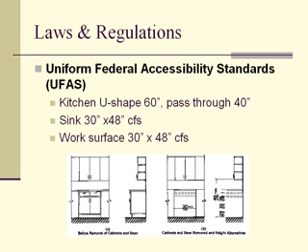The idea also is to provide the 30-inch clear floor space that we have spoken about at each of the appliances: the washer, the dryer, the refrigerator, the range. There is also a specific requirement to provide a sink that has a 30 by 48 clear floor space below it, which is diagram B, where it is totally clear below, allowing somebody to approach that sink in a forward manner and have the knee clearance that we spoke about in the past.